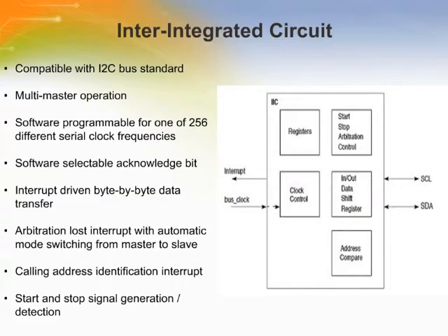The I2C bus is a 2-wire bidirectional serial bus that provides a simple, efficient method of data exchange between devices. Being a 2-wire device, the I2C bus minimizes the need for large numbers of connections between devices and eliminates the need for an external address decoder. It has two signals, IIC SCL, the serial clock line, and IIC SDA, the serial data line.